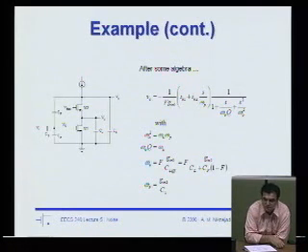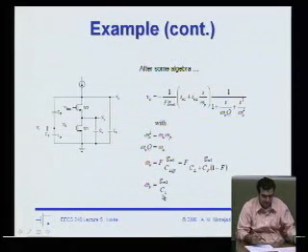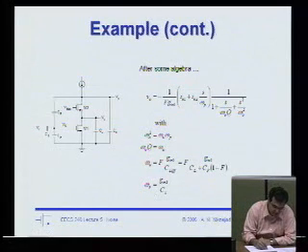Anybody want to take a guess? Omega t, because it can't go further than omega t. That's gm over Cgs. That's right. So the upper bound would be omega t, the unity gain frequency, because Cx is basically a bunch of parasitics.